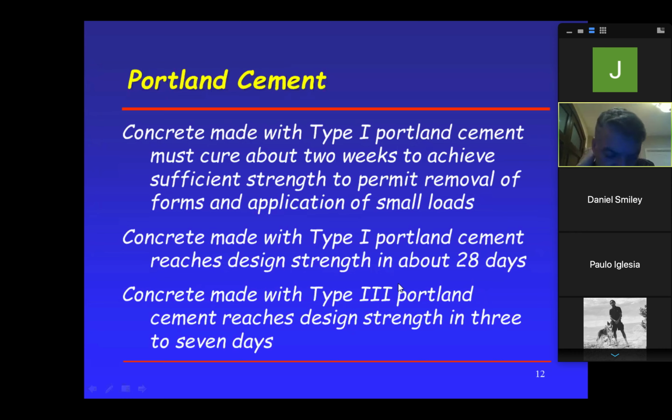Let me get off on a little tangent again. We did a parking structure. I did many parking structures before. So the contractor pours the beams on Thursday. This is typical standards out there. Now remember, the beam is 63 feet long, about 20 inches wide by 30 inches deep. Just visualize how big that beam is. Of course, a beam like that, we cannot design with conventional concrete like we're doing here. We have to use post-tension, and I'll talk about that a little bit later.